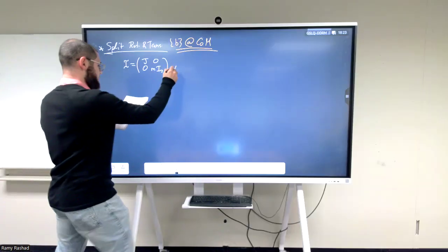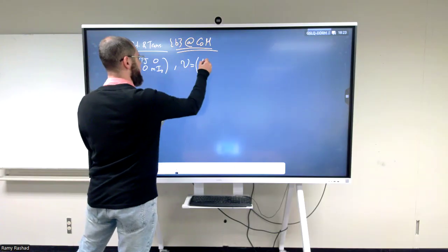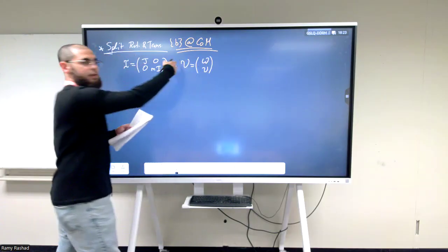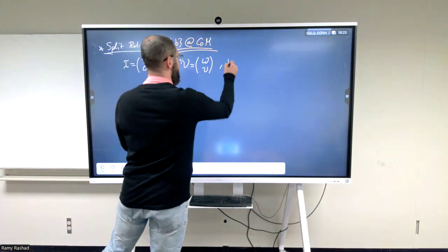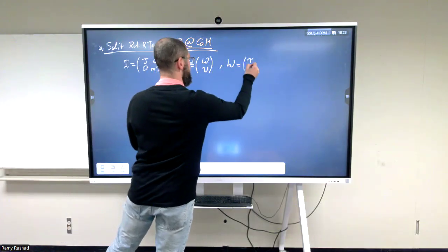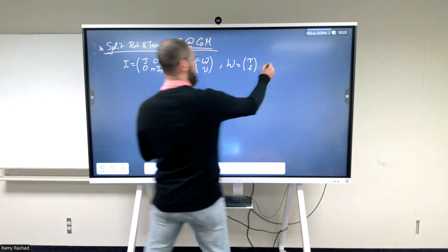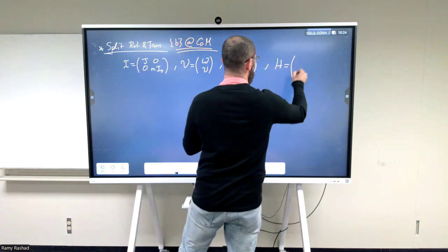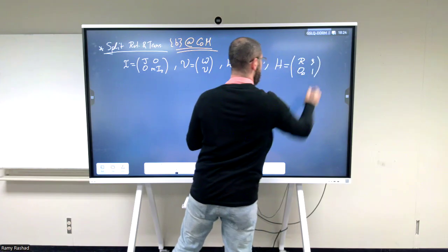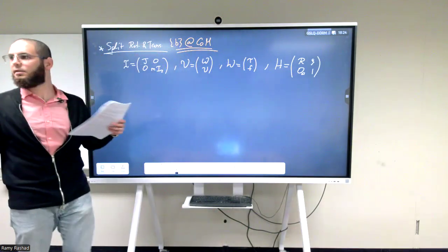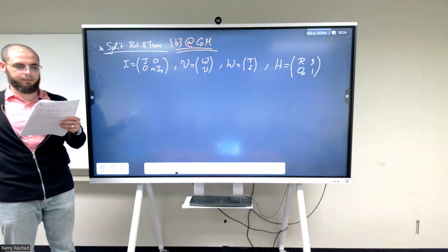And V now is equal to omega and v, so capital V here is the twist, and small v is the linear velocity component of it, and the wrench is simply torques and forces. Also remember that H itself was a 4x4 matrix that had a 1 times 3 and a 1 and the psi here. Of course, all indices where they should be.